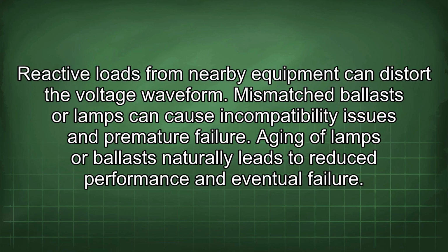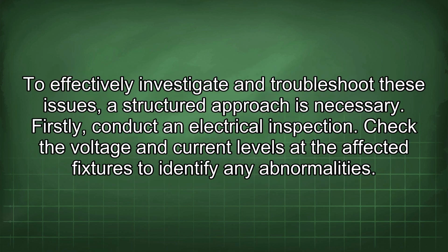Reactive loads from nearby equipment can distort the voltage waveform. Mismatched ballasts or lamps can cause incompatibility issues and premature failure. Aging of lamps or ballasts naturally leads to reduced performance and eventual failure. To effectively investigate and troubleshoot these issues, a structured approach is necessary.